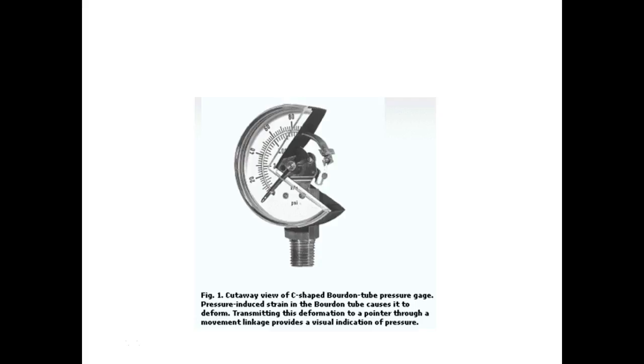If you don't have enough pressure in the system, then you're not going to be able to create the work. If you get too much pressure in the system, then you're going to tear things up, right? You could break the lines, you could press the seals on your actuator. You could cause things to explode.